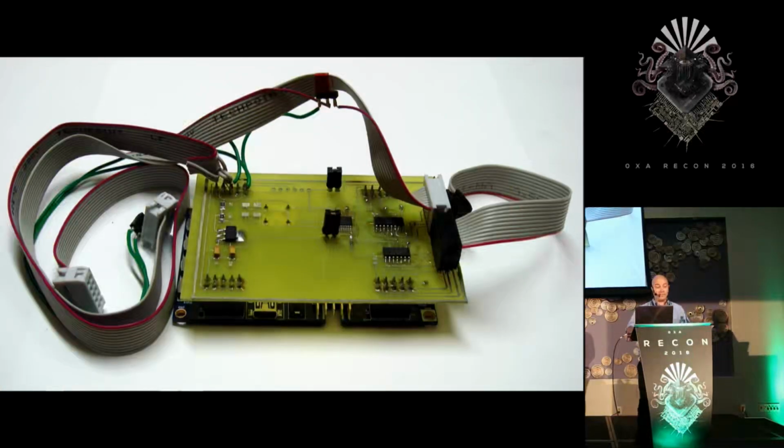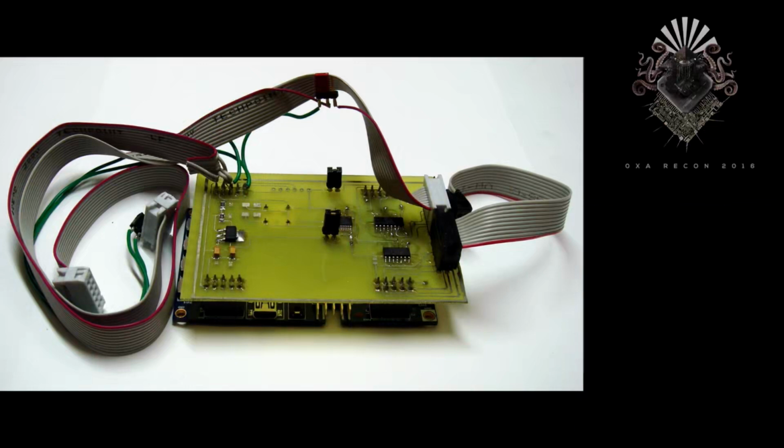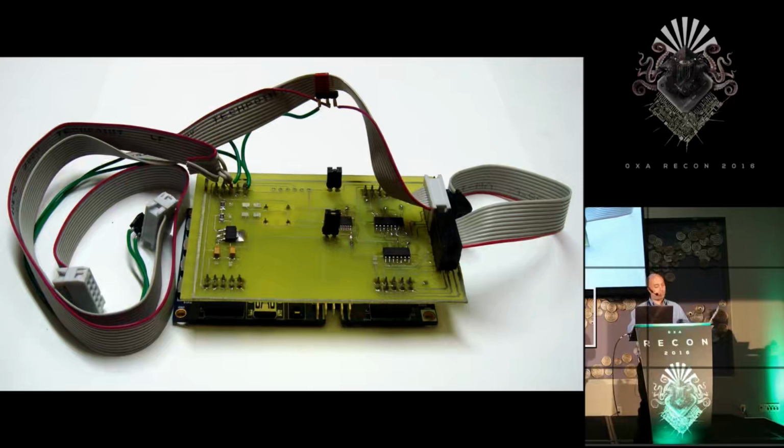Since I had an effective glitch, I took the circuit from the breadboard and etched a simple PCB that could plug directly onto the XMega development board. This performs exactly the same function as the breadboard did, but I'm a lot less likely to accidentally unplug a wire from the breadboard and have to repair it. The circuit was simple enough to create a one-sided PCB, so I just etched it at home.